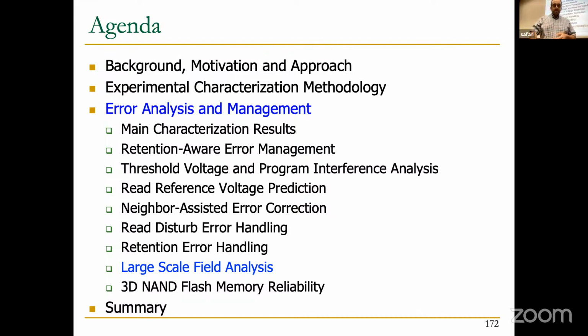Okay. So until now, all the techniques that I discussed in characterization were using that infrastructure, and we were instrumenting the real NAND flash chip. So basically, we were sitting on the flash controller with observation of flash chips, and we could do everything we want. We can optimize, adjust threshold voltage, read the calculated VPass, and all these things that I already covered.